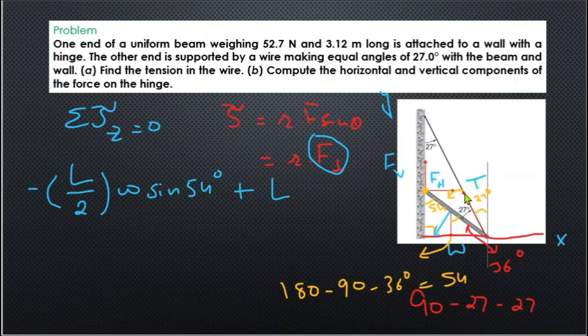Now, in that case, the torque is acting in that direction and I need the component of force which is perpendicular to this R or L according to this relation of torque. So my component of this tension force which would be perpendicular to this R would be something like that, and let's denote that with T perpendicular.